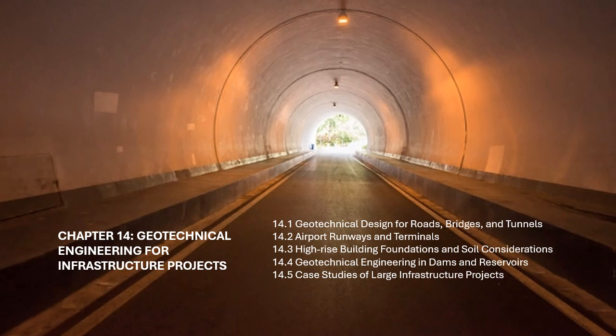14.4.5 Case studies in dam engineering. Several large-scale dam projects around the world demonstrate the importance of geotechnical engineering in ensuring the stability and safety of dams. Three Gorges Dam, China. The Three Gorges Dam, one of the largest hydroelectric dams in the world, required extensive geotechnical studies to evaluate the foundation conditions in the Yangtze River Valley. The foundation was designed to resist significant seismic forces, and seepage control systems were implemented to ensure the dam's long-term stability.